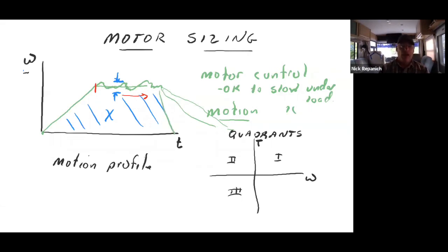And so now you're starting to think about controlling the deceleration of the motor, not just the acceleration. In that case, depending on how you're coasting, you may have to start applying negative torque and be down here in this area. That would be down in quadrant 4, right? If we applied negative torque and now had control of the deceleration rate.